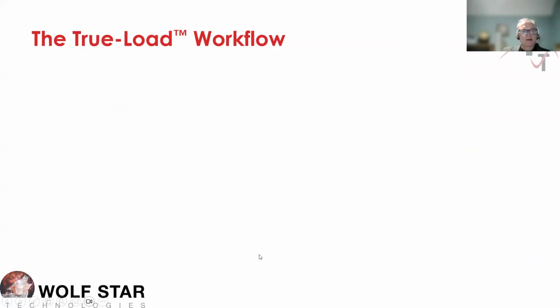So here's a workflow. This is how it all looks. We start off doing this process with your FEA model. This is your normal FEA model. And then what we're going to do now is have you put on unit load cases on this thing. We're not going to put on a complex loading environment. We're going to take your complex loading and break it down to the component loads.